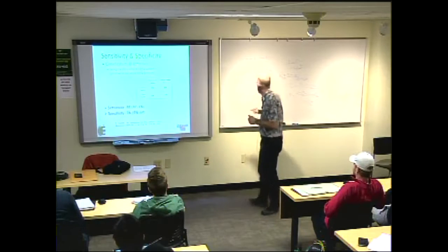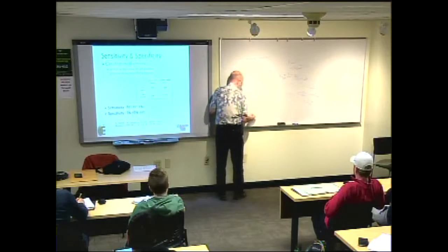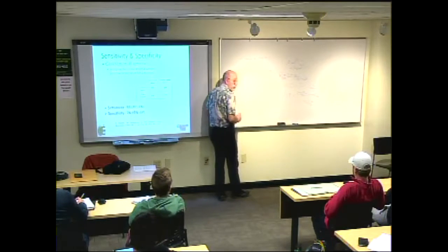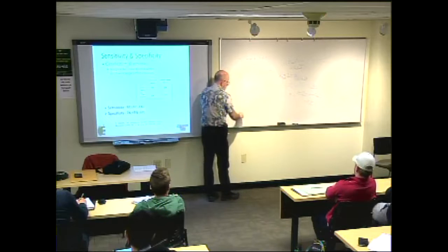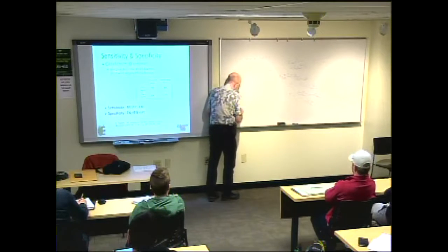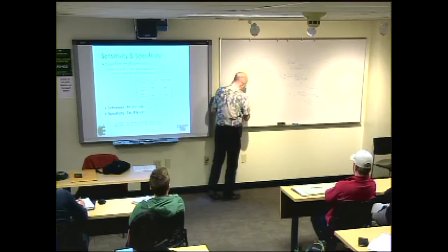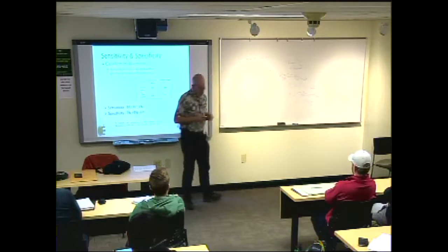The sensitivity is when we had a sensor that had a characteristic where there was maybe some concentration of some molecule we were trying to measure, and there was an output voltage, and the blank value was when we have a 0 concentration, but then there was the slope to this. And the slope was the sensitivity, and that's the word for sensitivity that's used in a chemical context.